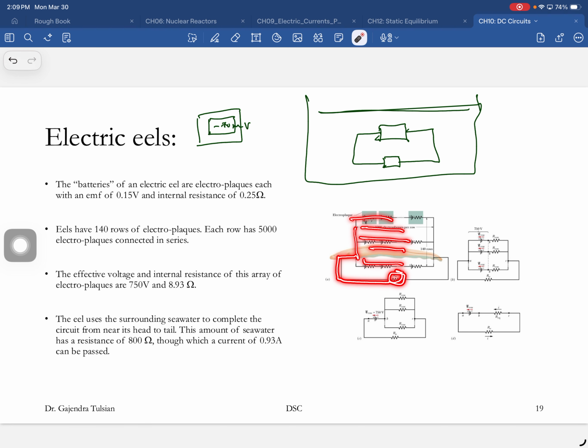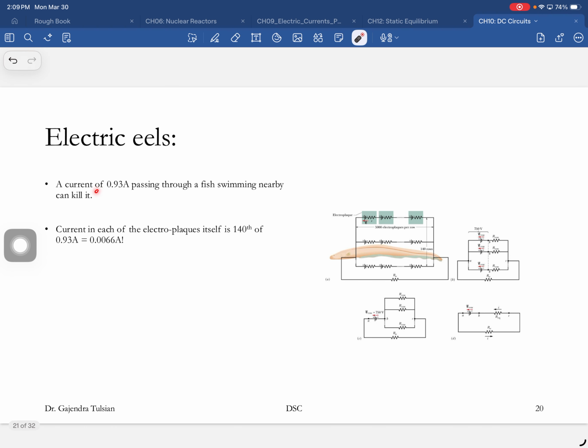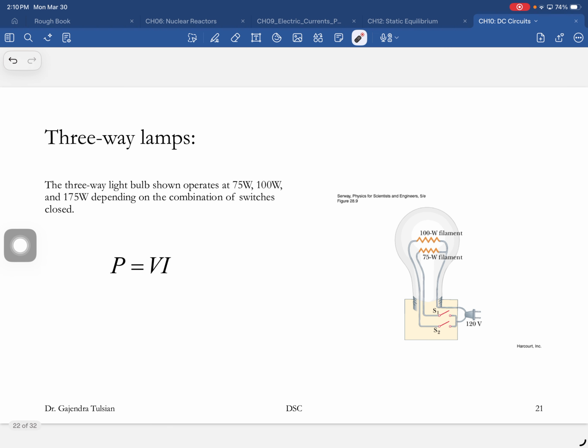Household wiring. So here's the power line, and like I said, every device is connected in parallel. So if this device goes bad, that device can function as well. And this way, everybody is seeing 120 volts. Houses are connected like that as well. Here's this house, that house, and if something bad happens to this house, that house can still get power, and so on.